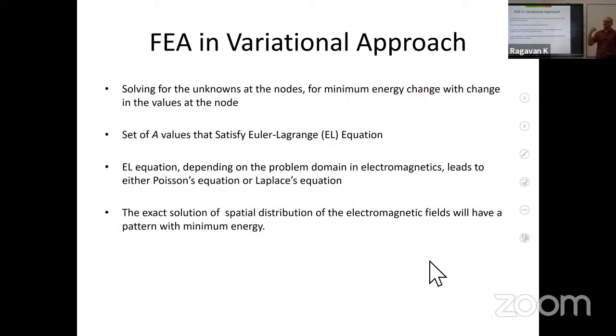Obviously, it will not be a high energy point. It should be an energy minimum point, right? If the fields go through low reluctance, we know that the energy value is minimum compared to any other case. By the simple expression half V square by 2 mu naught, we can apply that and see the solution corresponds to minimum energy. And the Euler-Lagrange equation also says it is a stationary point. So that way we can justify it. There is another equation that we use to say that fields take the minimum energy pattern.